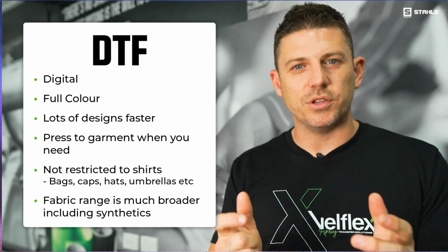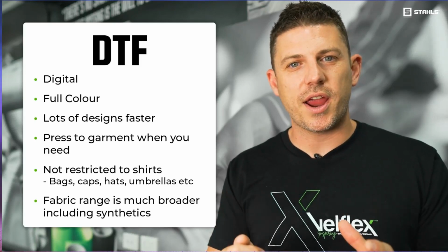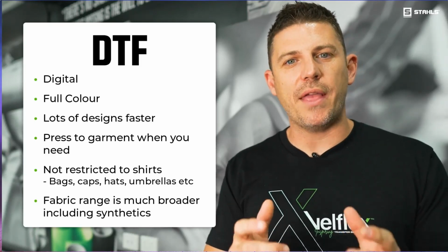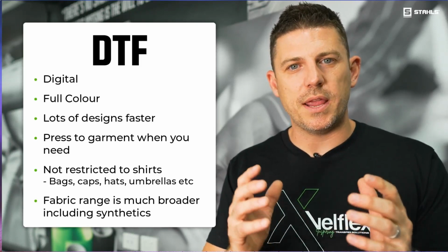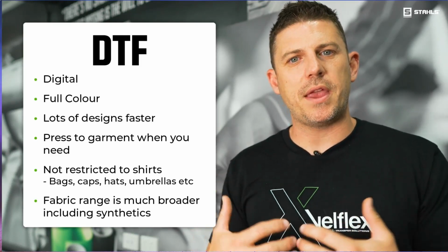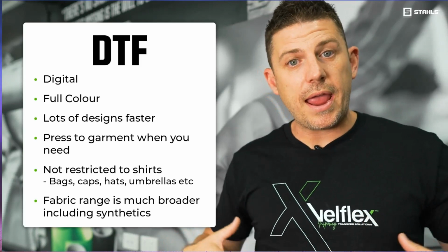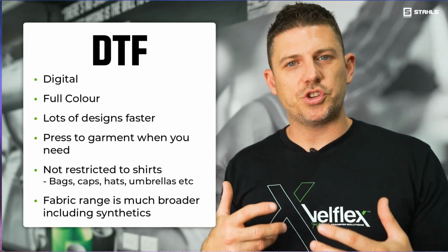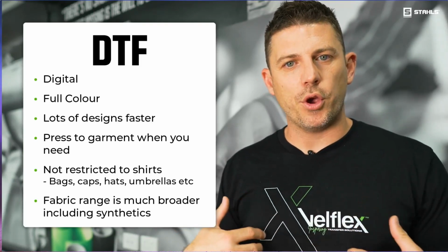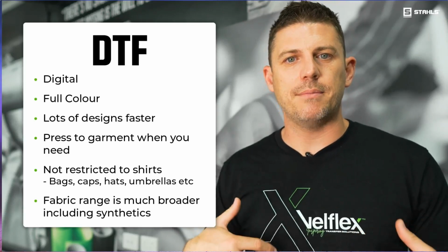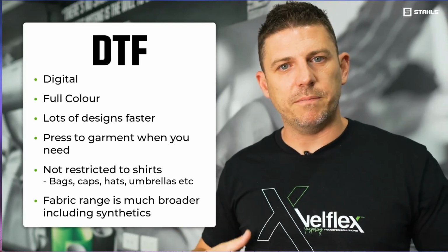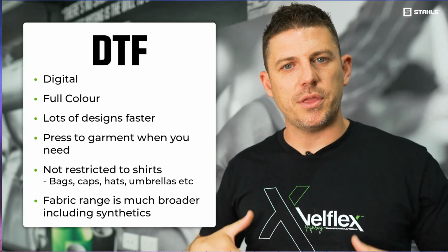Now guys, there's some massive other benefits around DTF over your DTG when we're stepping up to DTF, is because we're printing it onto a carrier, because it's now a transfer, we can now apply that print onto so many more locations on a garment. When we think about DTG, even screen printing, we're really restricted to the placement of where those prints go, okay? They can't be near seams, that sort of thing. They've got to be in the middle of platens and middle of the shirt and things like that.